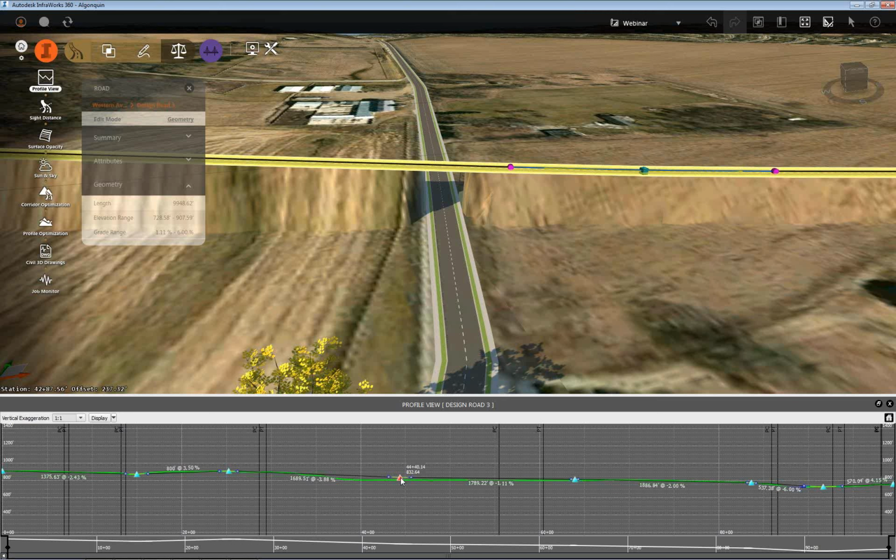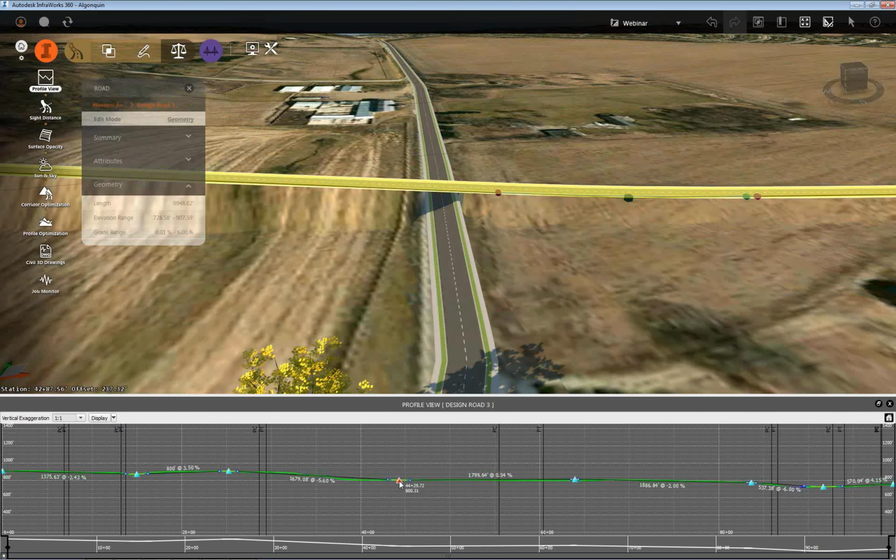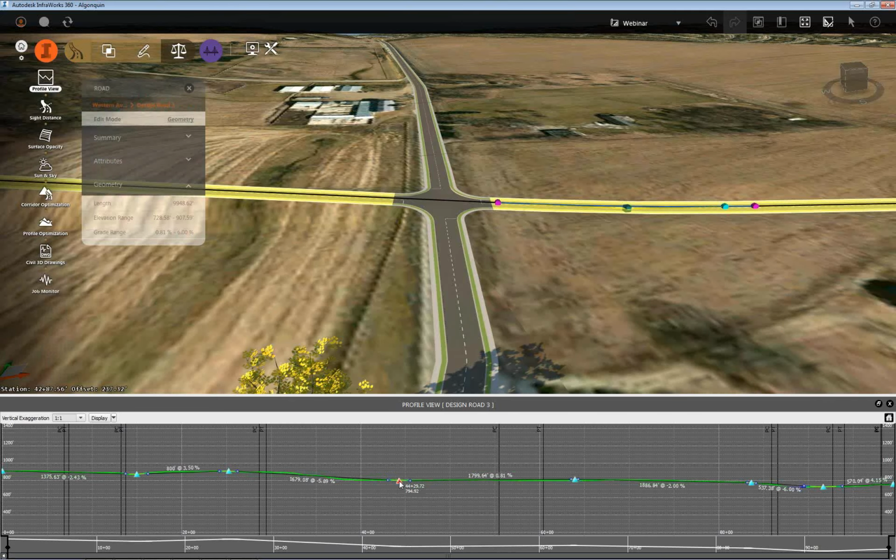So what we're going to do at this juncture is I'm going to take a look at our vertical and refine anywhere that I think is necessary. So the overpass is not something I need, so I'm just going to come back and place it closer to grade. And we're going to get it down here. Okay, it automatically creates that intersection for me. No problem. Now this isn't a bad situation here. That's a lot better than what we had.